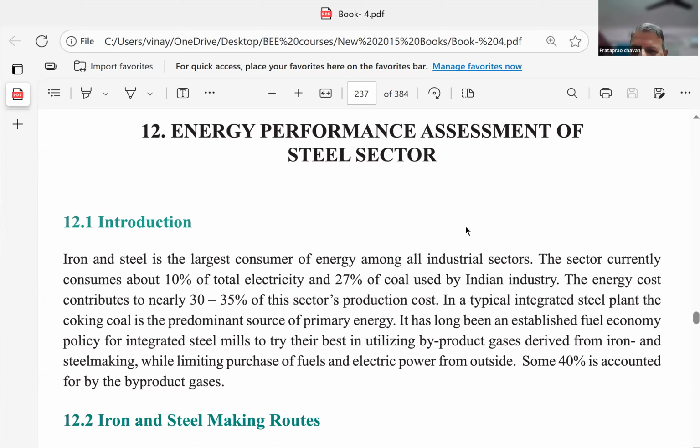Boilers have an efficiency of about 85%. That means if 100 units of heat is generated by burning the fuel, 85 units are converted into steam heat. The remaining 15% is carried away by the waste gases. In spite of whatever recovery mechanism we apply, we still could not recover the 15% that goes out of the chimney.